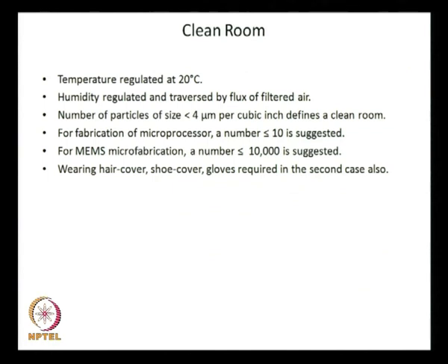Now, before we get into this microfabrication process further, I must tell you, you have heard of a clean room, that you have to have a clean room to do microfabrication jobs. If you go to the definition of a clean room, the temperature has to be regulated at 20 degrees centigrade, and humidity regulated, and it is traversed by a flux of filtered air.